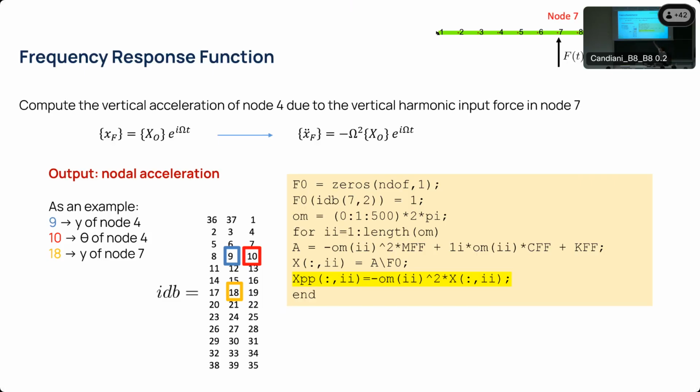So we already have the frequency response function matrix of the displacement of the various 3 coordinates. You can compute the frequency response function that links force to the acceleration of the various nodes by multiplying it by minus omega squared. So you will get a matrix. Each of the terms will be multiplied by minus omega squared at that specific omega. Then you will multiply it by the vector of forces, and then you will get what we call the accelerances of the various nodes.